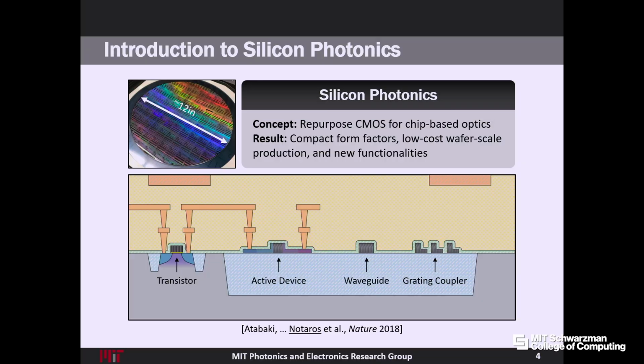And then, okay, we can guide the light on the chip, we can modulate the light on the chip. Now we want to interface with the surroundings of the chip. So to do that, we would pattern some more interesting, more complex devices. Maybe something like these grating antennas, which we'll talk about in a few slides again. The idea there is you have your waveguide on the chip. Now all of a sudden you want to scatter the light up and out of the chip to interface with different things in the environment. For quantum computing, that thing would actually be the physical qubit that you're trying to interface to.